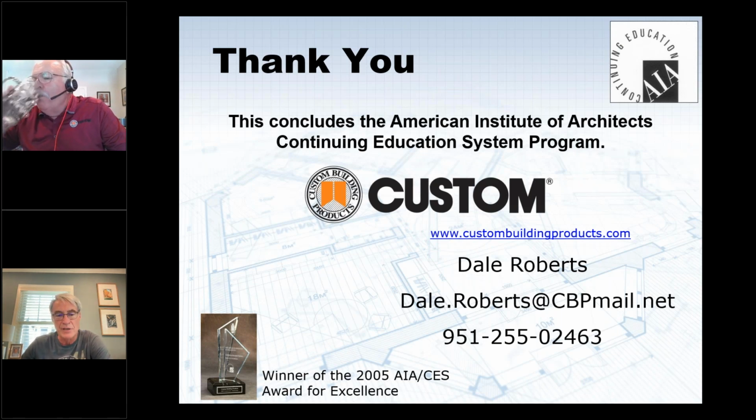Lots of great information there, some of it basic, some of it more detailed, and I think it's great. I do have a few questions here, and I want to run through this with you. So our first question, Dale, is: if you run the backer board over the tub flange, you will have lippage issues with the final tile install. Is it acceptable to set it on the flange and use a waterproof membrane over the gap?